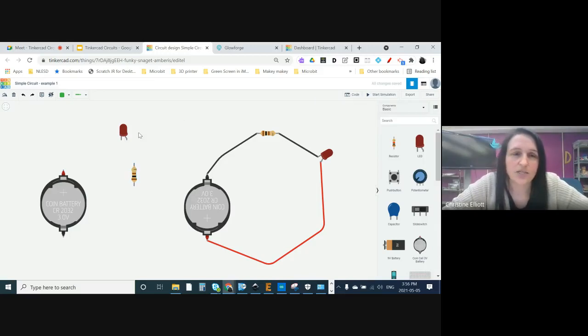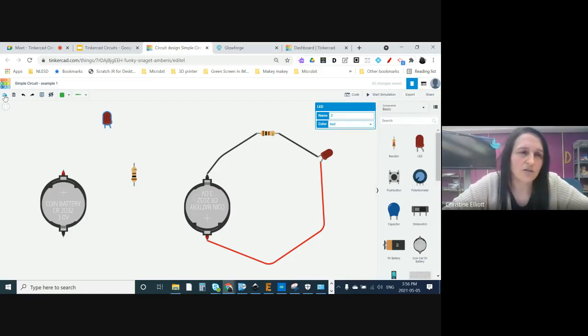Now, if I want to connect these together, if you click on any element and you don't like the way it's oriented, you can come up here and rotate it. That's your little rotate feature here. So you click on any item, you don't like the way it looks, you can just rotate it all the way around. Now, I like using quick keys. The quick key for rotate is just R. So on my keypad, I'm just hitting R and I rotate it really quickly.